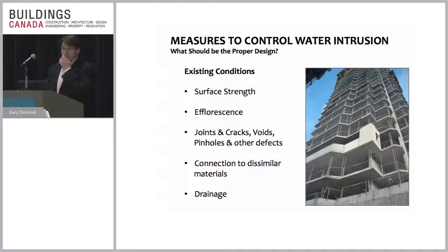In terms of existing conditions of the building or what has to be retrofitted, surface strength, efflorescence, does that have to be cleaned? How's it going to be cleaned? Again, dealing with the joints, the cracks, the voids, pinholes.